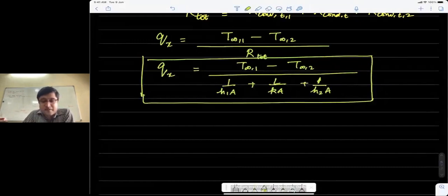We started from there itself, because if it was not steady state, the temperature can change locally. T_A and T_B can also change. So this is actually at steady state. At steady state, this is the amount of current you can pass through, but not in the intermediate time, because in the intermediate times temperatures locally can change.